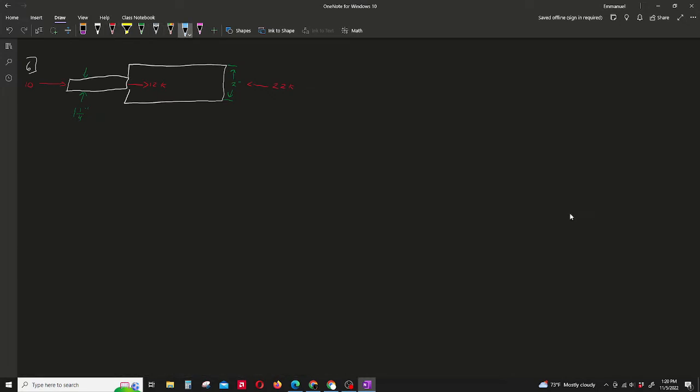So number 6, we've got a load here. I'm gonna do segment A side first. Let me just plug that in here. A is gonna be, we have a load of 10 kips coming in at location A. The area, and we'll just call this P, right? Area is gonna be 0.7854 times 1.25 squared. So that's gonna equal 1.23.